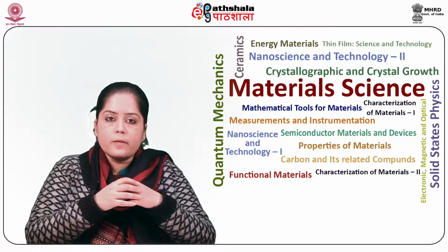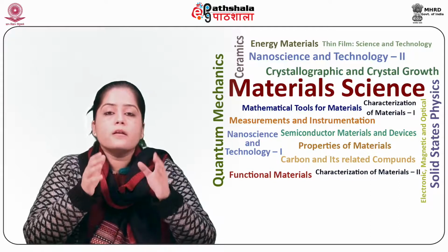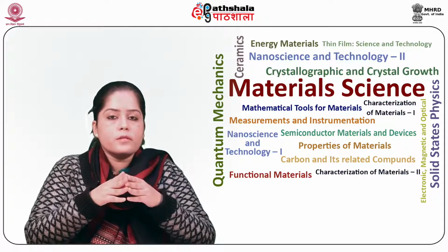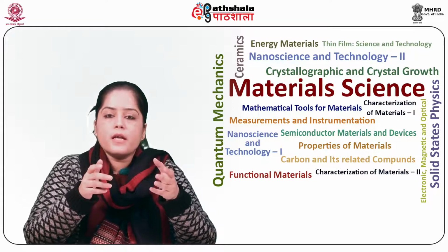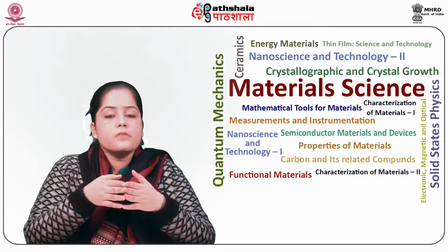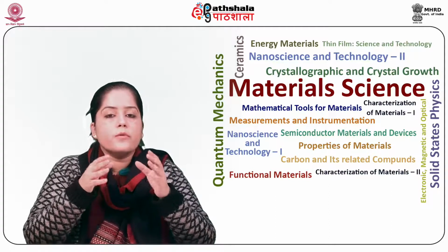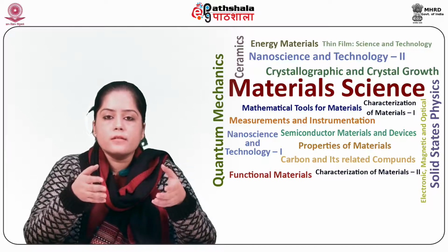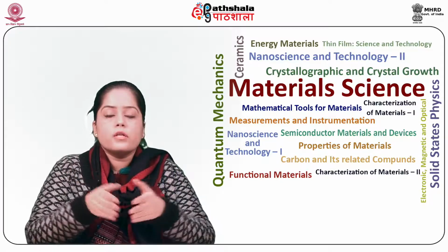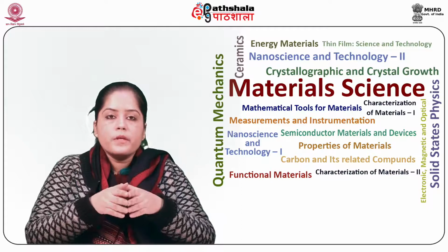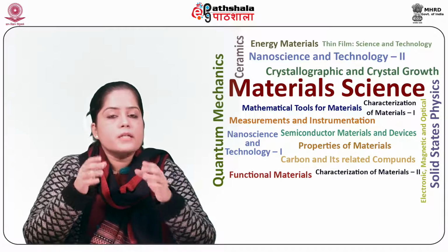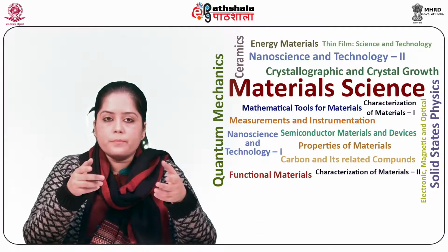Modern CMOS processing is a complicated process and requires a lot of understanding. A fair question from a designer would be, why do I care how transistors are made? In many cases, if designers understand the physical process, they will comprehend the reason for the underlying design rules and in turn use this knowledge to create a better design. Understanding the manufacturing steps is also important when debugging some difficult chip